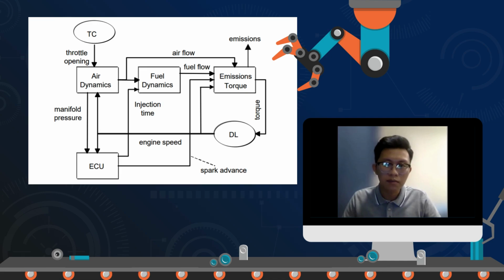The in-cylinder process for torque and pre-catalyst emission estimation has been characterized using black box neural network models, based on the synthesis of steady-state experimental data, due to the requirement to limit the computing time with adequate precision. An engine control unit module, which is an ECU, has been developed in order to simulate the effects of different control strategies. The main objective here is air-fuel ratio control in order to guarantee optimum catalyst performance, especially in control transients because of the different dynamics of air and fuel flow.